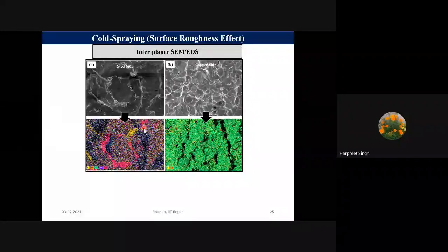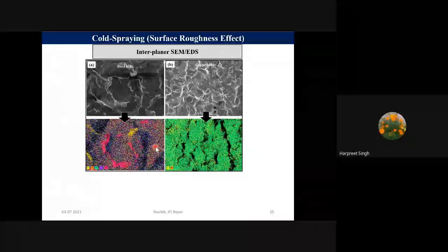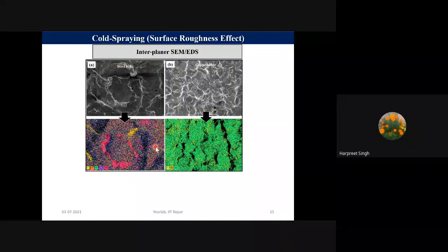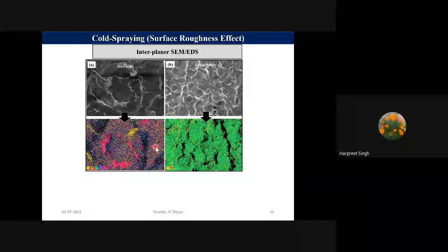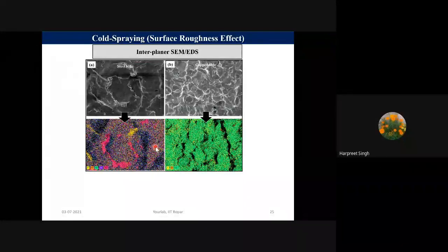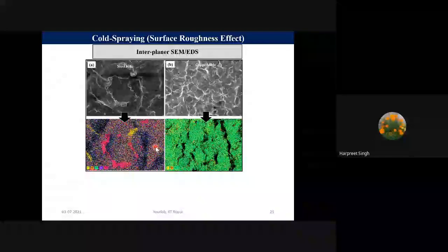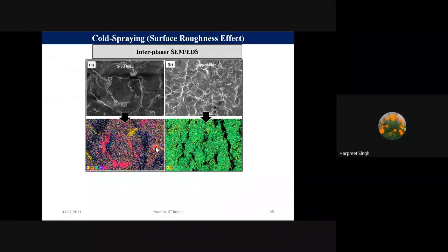So that means this is giving some information about the jetting, which is that there was some kind of merging of copper into the steel side and vice versa. And when we broke them in shear, these elements were shared between them, right? So this gives us an idea about the jet formation, and even metallurgical bonding indications.